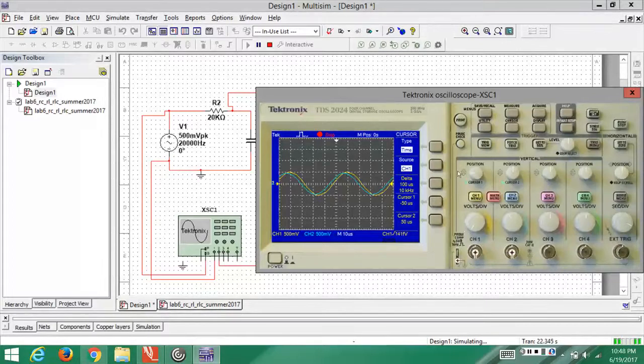You can see it because they are at the leftmost and the rightmost position of the screen. I need to bring them to a convenient place where I think the cycle started, and the second cursor to a place where I think the cycle ended. To move the cursors, you have to use channel 1's vertical positioning knob and keep it moving.